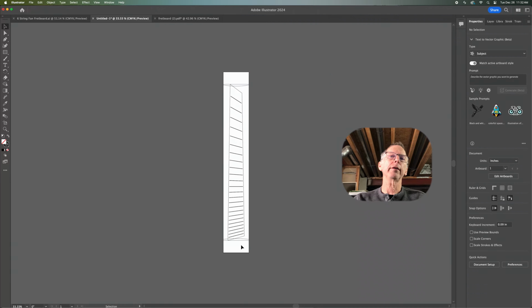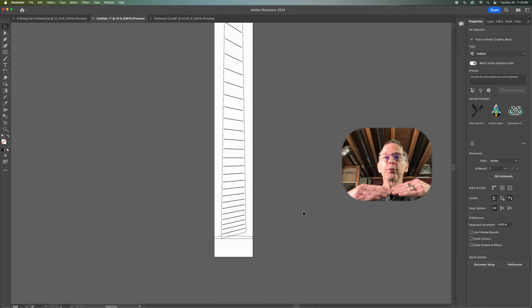Now there's one other thing I need to do, and that is to indicate the bottom of the fret slots on this template, because the bottom of the fret slot is going to be radiused. I typically don't radius my fret slots, and I'll probably talk more about this as I'm making the fretboard later on, but I know a lot of folks like to radius their fret slots. So I'm going to build this model to include a fret slot that has a radiused bottom, so you have that option if you so choose.